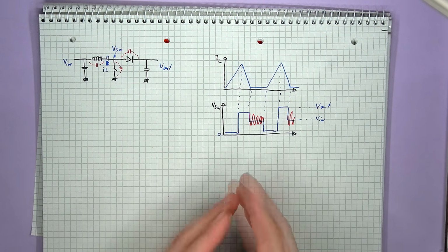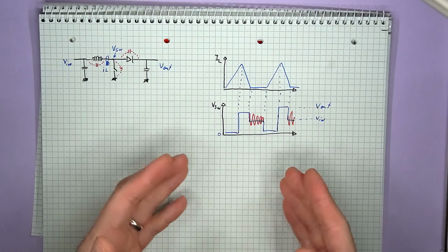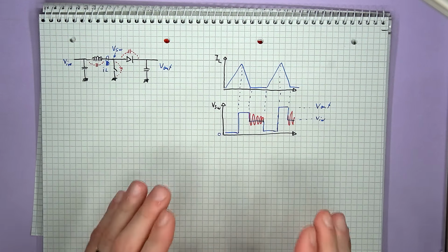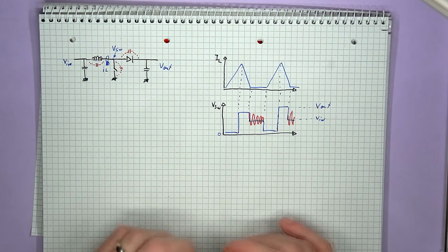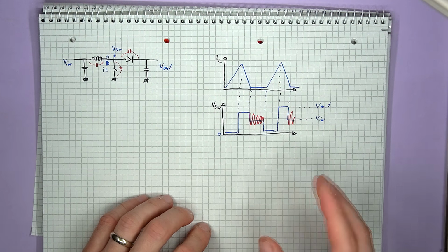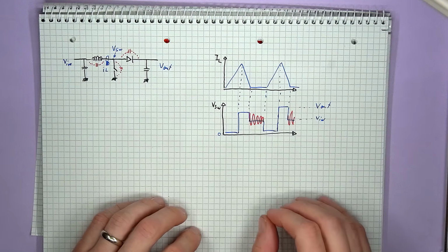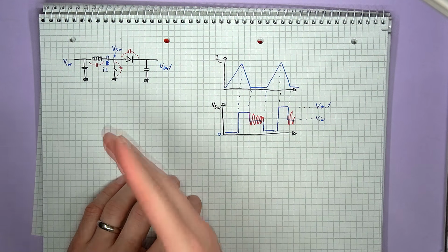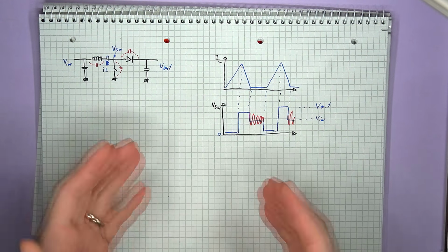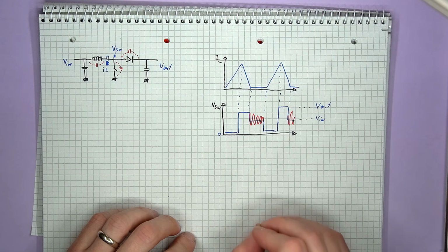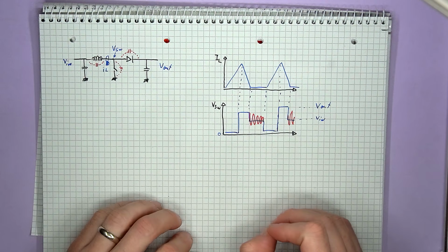So even though you don't want to see this sort of effect, seeing an oscillation in the switching node in converters running in discontinuous conduction mode is perfectly normal. This is typical for any converter. So you'll see this oscillation in buck or boost or any other converter. So even if you don't have the possibility to directly measure the inductor's current, as probes are quite expensive, seeing this sort of oscillation is a telltale sign of the particular conduction mode.